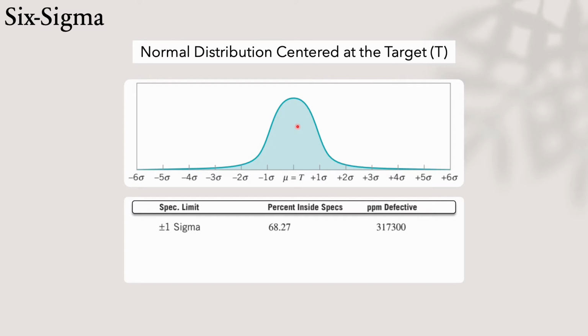So in terms of the manufacturing process, if our acceptable range is between plus minus 1 standard deviation, the conforming or acceptable products that will fall within that range is 68.27%. It's not a good percentage of conforming products, because the defective or non-conforming products will be 31.73% in this case, right?